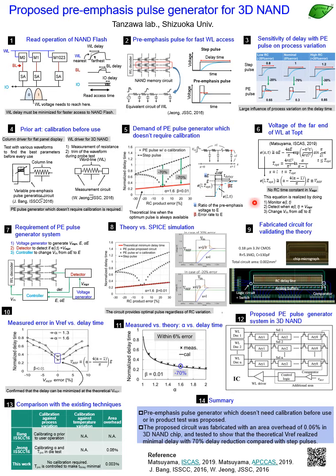So all the behavior is scaled by the RC time constant in the horizontal axis, but there is no change in the vertical axis. Therefore, you just need to monitor and detect the farthest voltage, whether the farthest voltage reaches Vref.